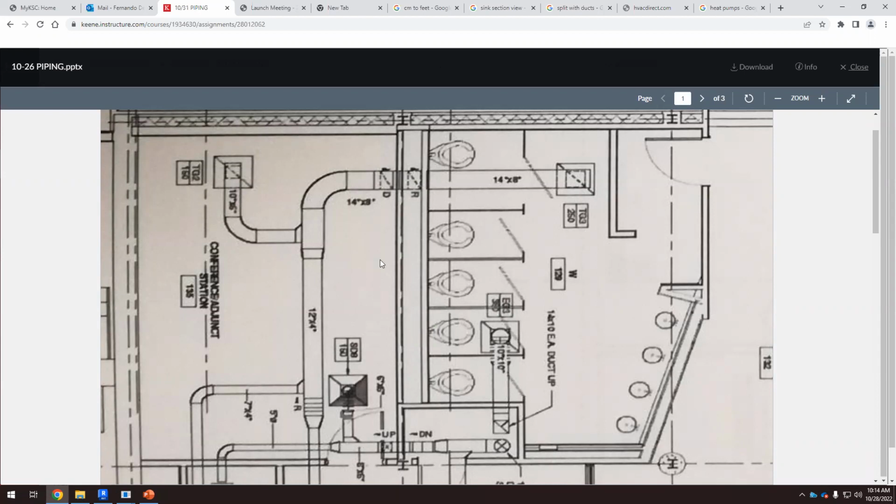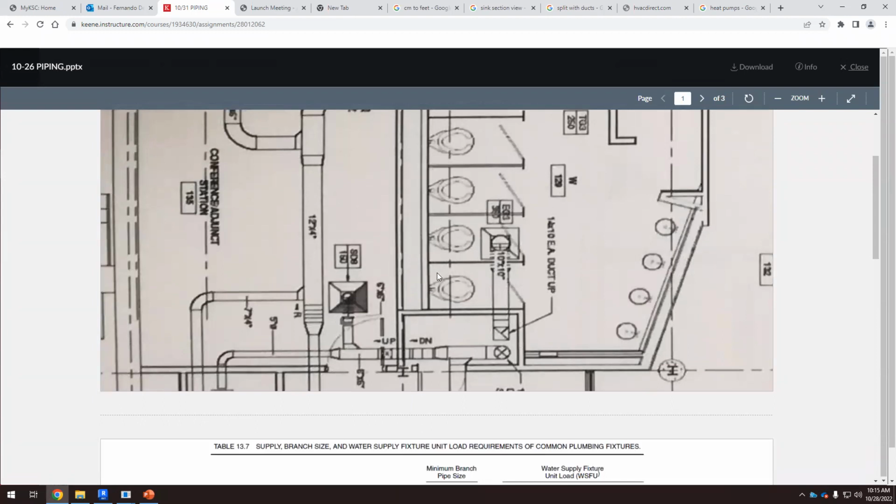The cavity works well because we need pipes going up and down where the toilets are, and then we need to provide more acoustic insulation. So if we duplicate the elements, if we duplicate the walls, the acoustic insulation will be much better. We don't have a single wall like this. We have a double wall where the toilets are.